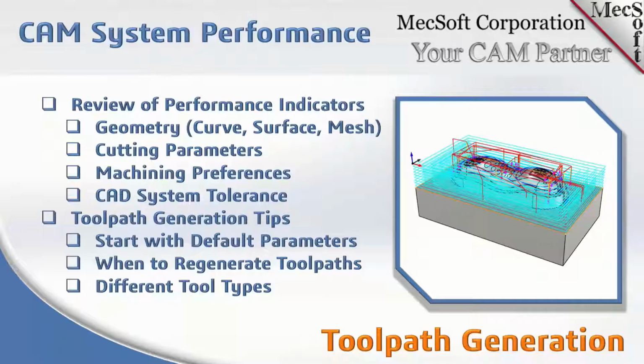So at least you'll know, well, this change that I made is causing an issue or not causing an issue. And then another thing that can affect toolpath generation is the type of tool you're using. Obviously, you're not going to base your machining tool on your simulation. But if your simulation is taking a longer time, then look at the tool type that you're using.